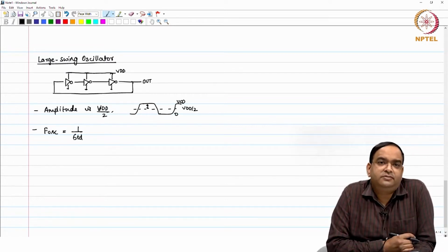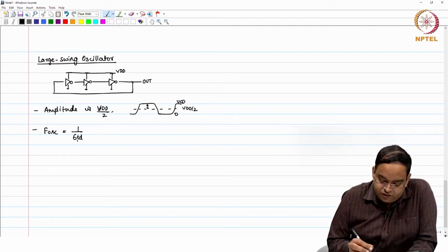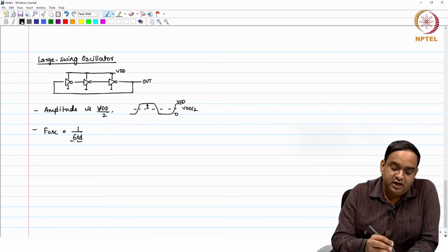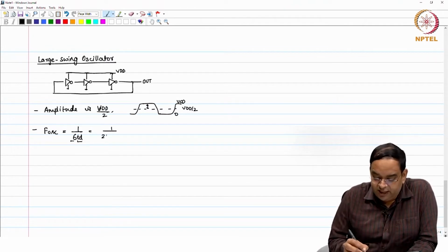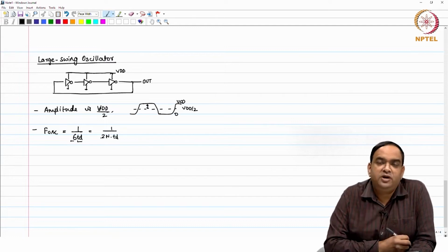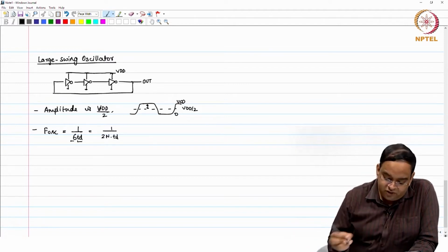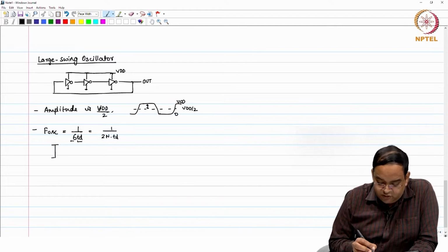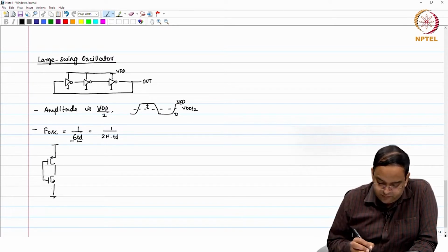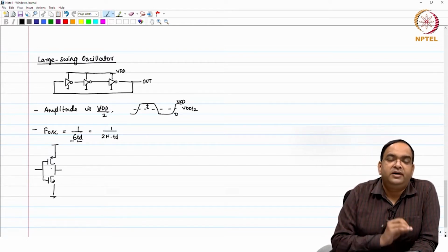What we need to find is, when we want to design an oscillator for the desired output frequency, we can choose TD or we can choose the number of inverters. Both these parameters are tunable. Which parameter you can tune and how much, that is something we need to understand while changing the frequency of the oscillator. So, let us say you choose a certain technology. In the given technology, you will design an inverter for the highest frequency possible.